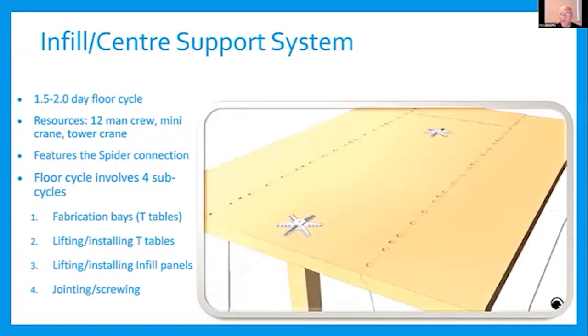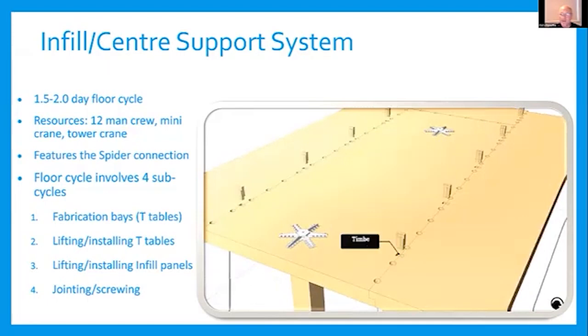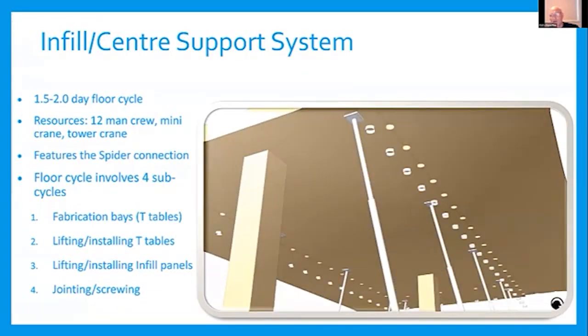Andrew will talk more about connectors, but these CHS connectors and these bow tie shaped things help pull the panels together and help deal with tolerance variance between the different panels. The couplers help try and transfer load. They have to be connected on the underneath and on top.